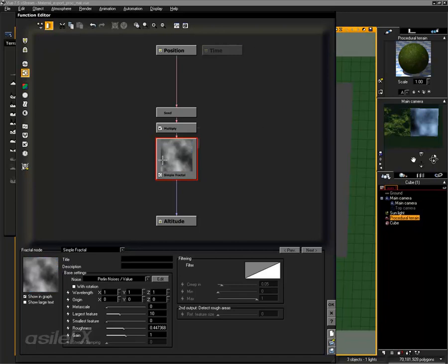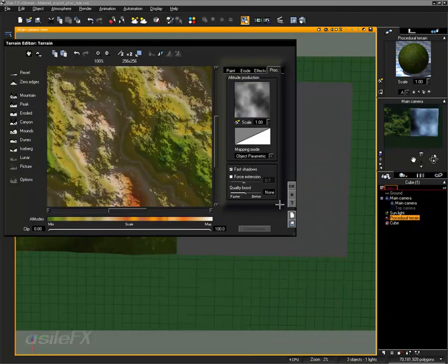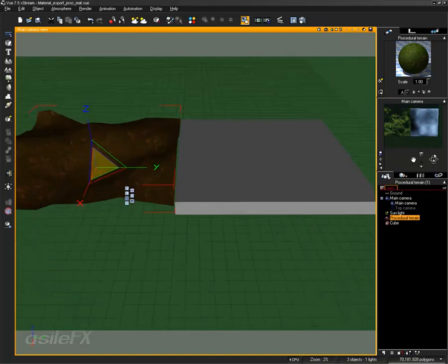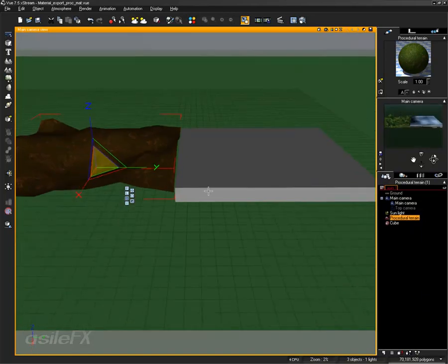So if we switch this to the 2D plane mode, we're going to see what's actually showing as part of the procedural terrain. It takes a slice from the fractal, in this case, since we're using a fractal. Whatever function you're using, it'll just slice out from the origin and then extrude from there. Materials, however, because they exist in the complete 3D space, the fractal moves through them, and your output is going to be a little different. Now, if this is matched its scale correctly and the Z position, then no other modifications need to be made.